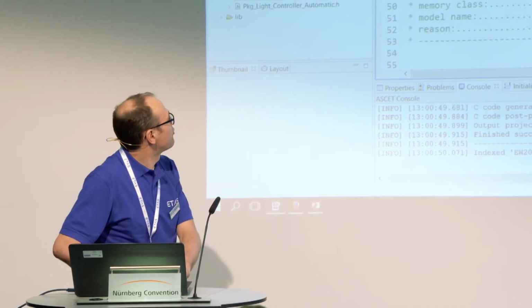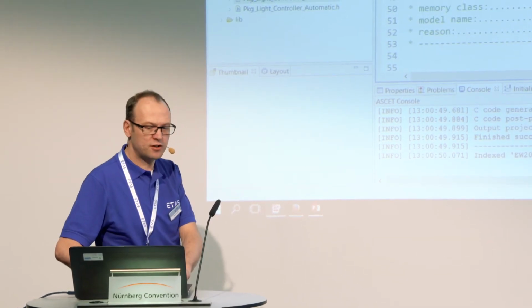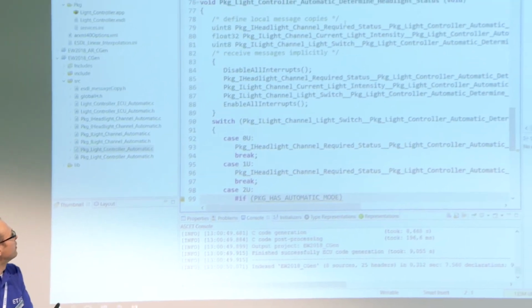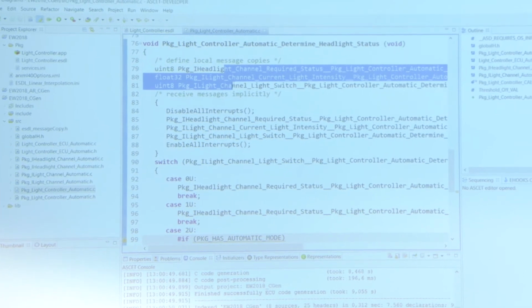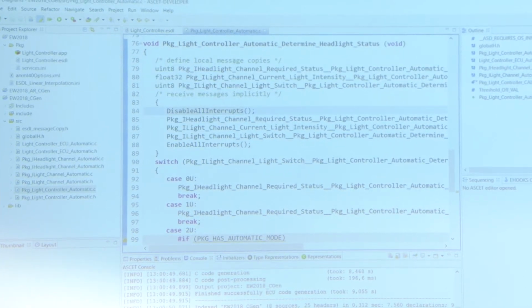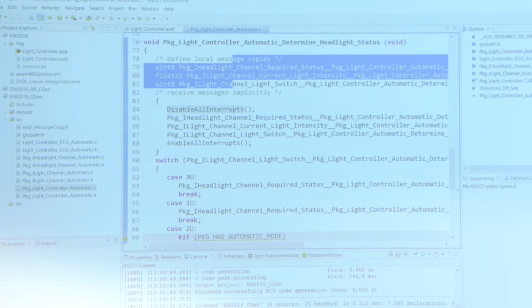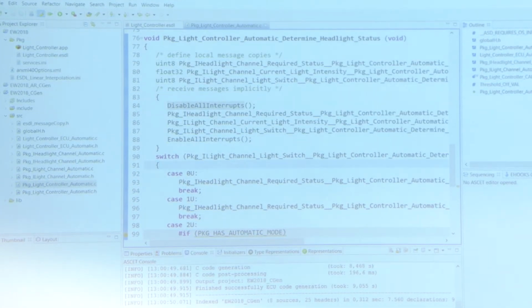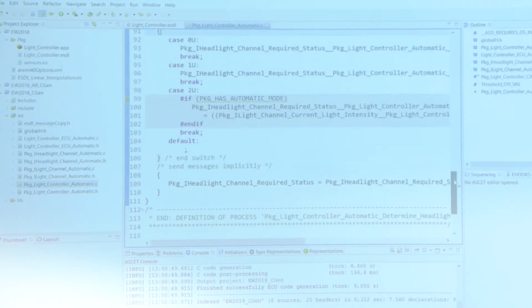There's my calibration constant. It's plugged in const volatile, because I'm going to modify that with calibration. And there is my actual ASCII code. These are my reads of my values. So this is creating a cache for all that data that's concurrently shared. This is going to populate that cache. It's going to do these calculations here based on those values.